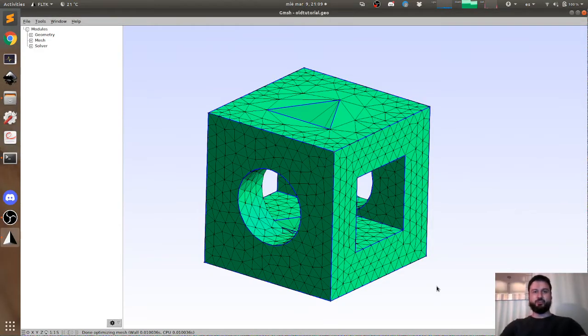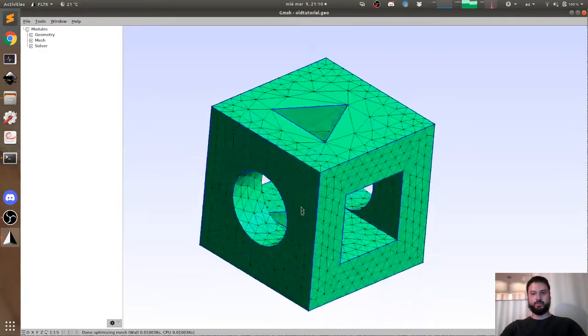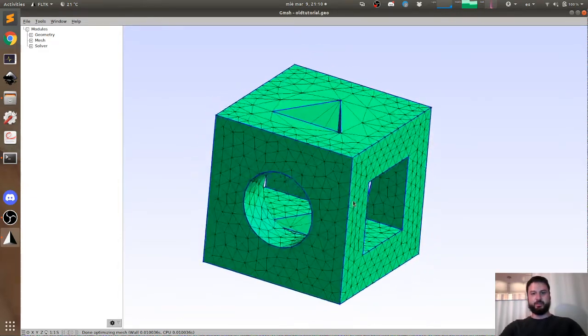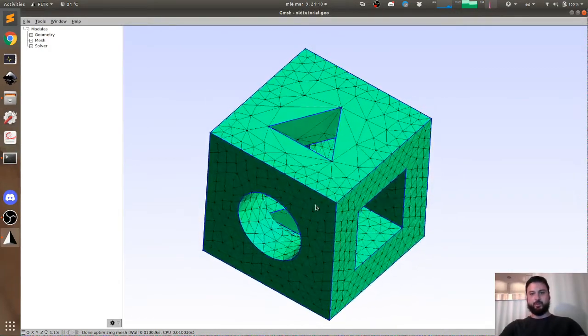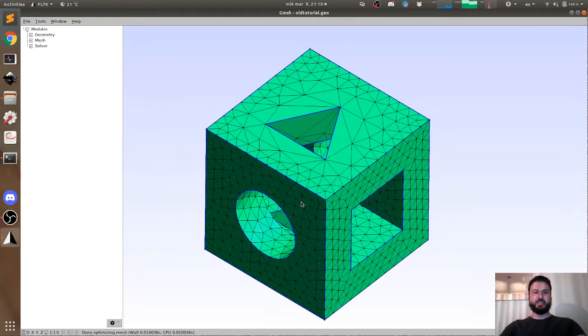Hello, in this tutorial I'm going to teach you how to use Gmsh to create a geometry and then mesh it into a finite element mesh. So two concepts here. One is the concept of geometry. Geometry is the shape, so we're going to create something like this, where the geometry is given by the outline shown in blue. It's the general shape, whereas the mesh is the discretization of the geometry. That is how we subdivide that shape into finite elements.